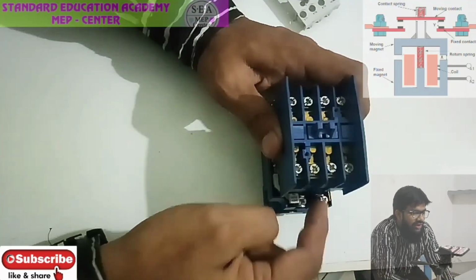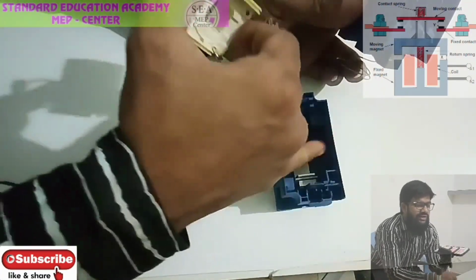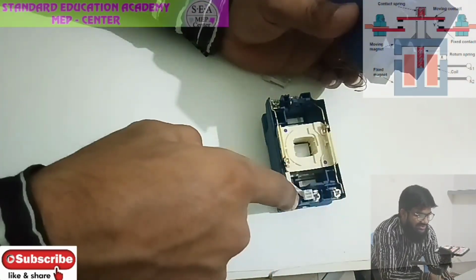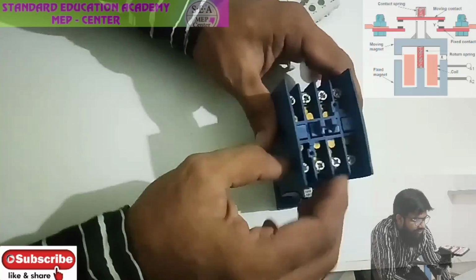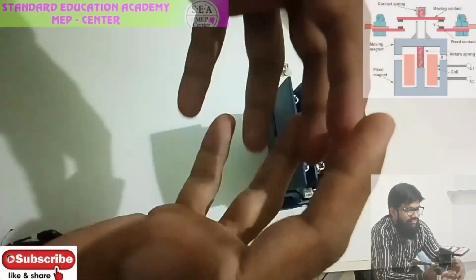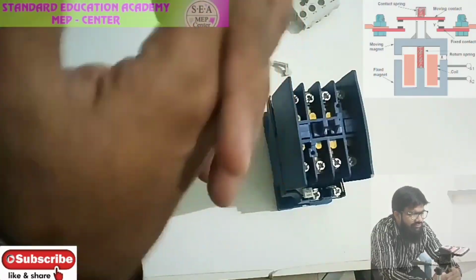Important is, energize the coil. When you energize the coil, electromagnetic effect will be created in the fixed part of the contactor, due to this particular coil which is getting energized by the power supply. As it gets the electromagnetic field effect, automatically this spring tends to move the movable part from the topmost place to the fixed part. When the fixed part and moving part get interlocked, due to its interlocking, we will get the supply from L1, L2, L3 to T1, T2, T3.